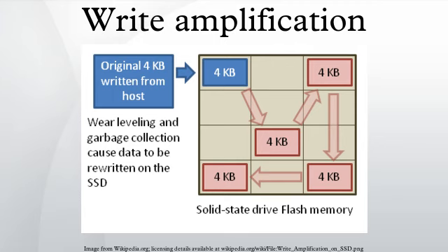Random writes. The peak random write performance on an SSD is driven by plenty of free blocks after the SSD is completely garbage collected, secure erased, 100% trimmed, or newly installed. The maximum speed will depend upon the number of parallel flash channels connected to the SSD controller, the efficiency of the firmware, and the speed of the flash memory in writing to a page.